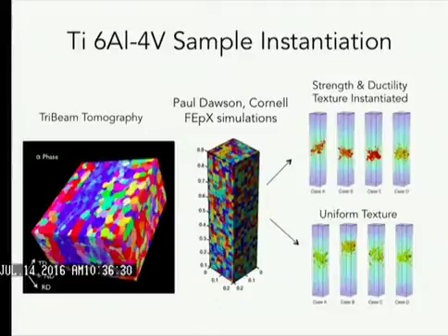So instead of doing that, you can analyze this data set, take out all the distributions of the sizes and orientations of the grains, and now make a virtual sample. Just sample from the distribution and reconstruct a virtual sample. And that way, you can do more parametric studies of what the importance of certain things are, and make virtual samples that are representative of what you've measured here.